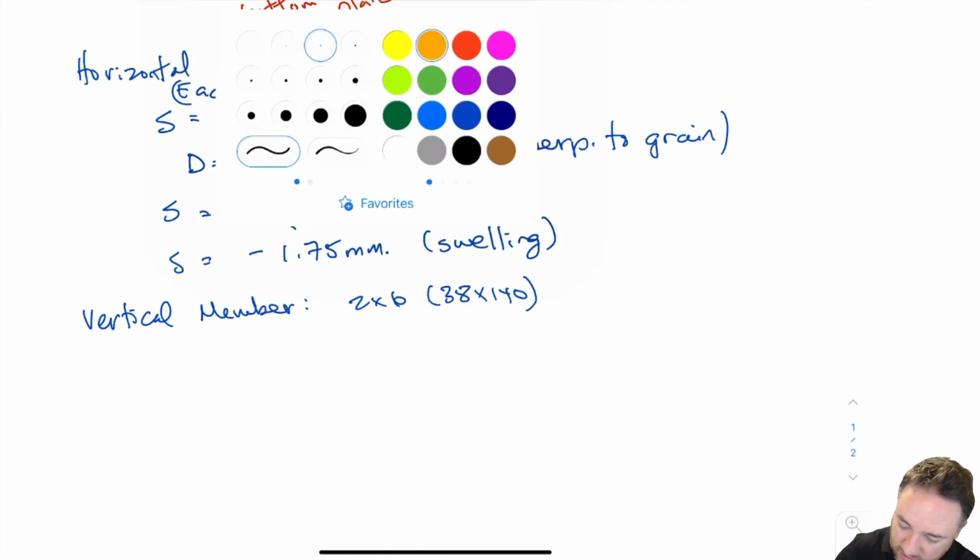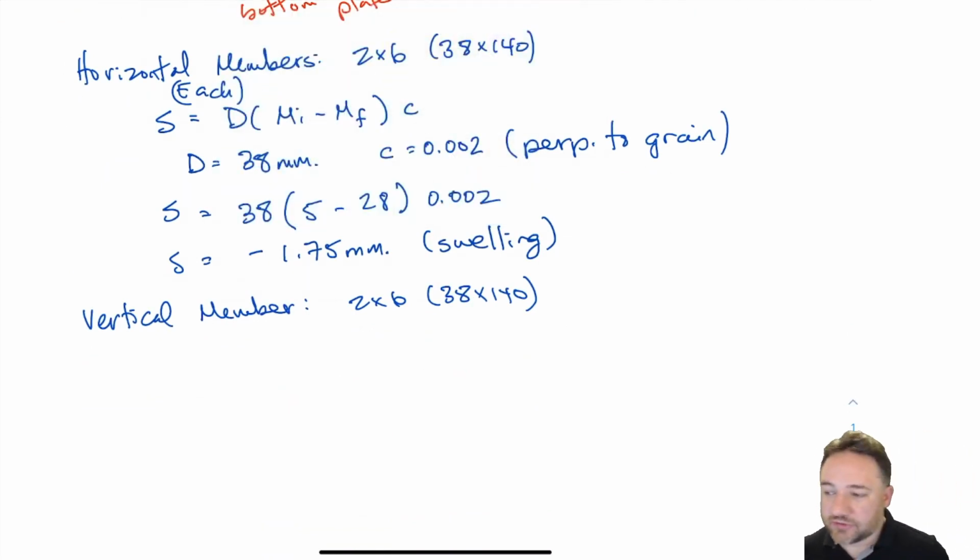So just to remind ourselves about how we convert feet to millimeters: we've got 12 inches in a foot, and each inch is 25.4 millimeters. That's something that you really have to put to memory because, especially in wood construction, we sometimes run into things that are in inches instead of in millimeters, and we need to know how to convert them. The only thing that you really need to remember is 25.4 millimeters per inch, and you can be just fine.